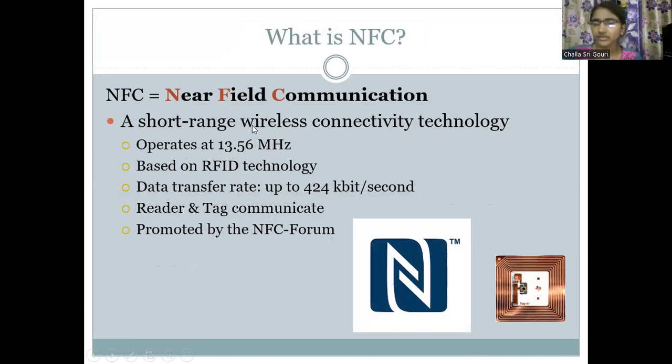Now, coming to its specifications, this particular technology operates at a frequency of 13.56 megahertz, and it is based on RFID technology. Recently, I've also made a video on this RFID technology, so to understand more about it, you can check out that video. And this NFC communication will help us in a data transfer rate up to 424 kilobits per second. And here, the reader and the tag will communicate with each other, and they are promoted by a forum known as the NFC Forum.